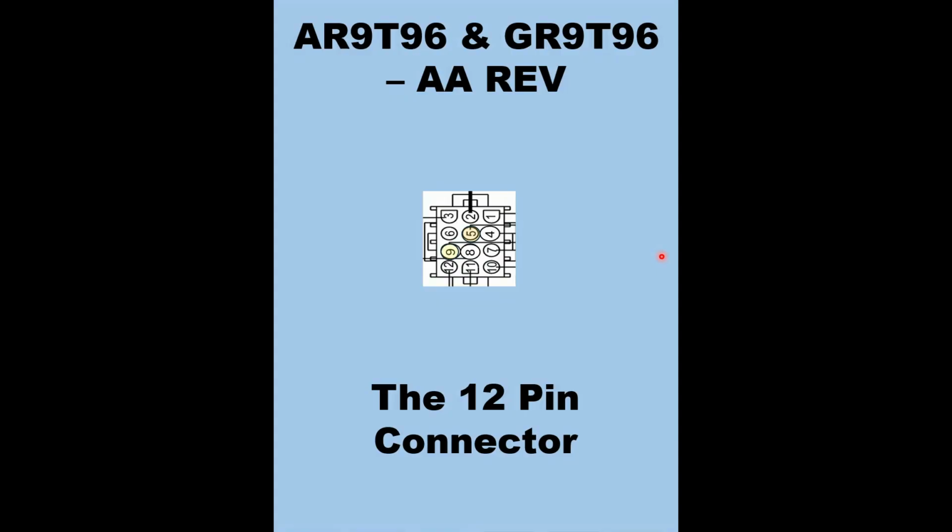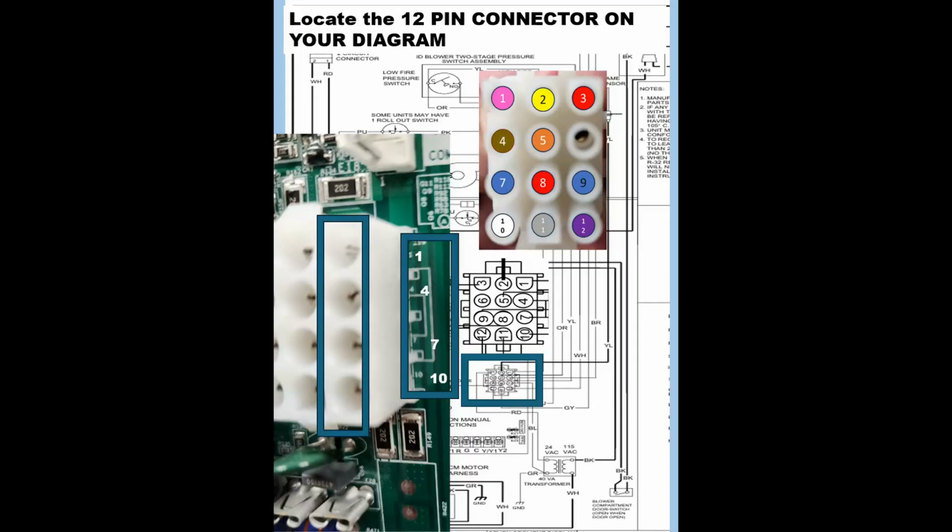And here we're just making the point about the 12-pin plug. You want to locate that. Make sure your numbers are correct. On the board here, you look down the side of it and you'll see these numbers, and that's the orientation of your plug. So just remember that whenever you're testing something, you want to be sure you have the orientation of the plug right. Because the plug only fits in one way, but that doesn't mean you can't flip it or have it wrong in your hand.